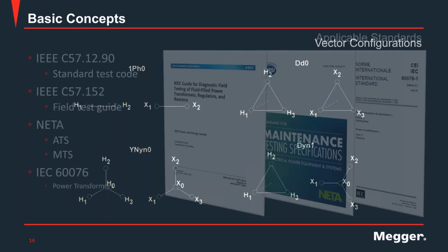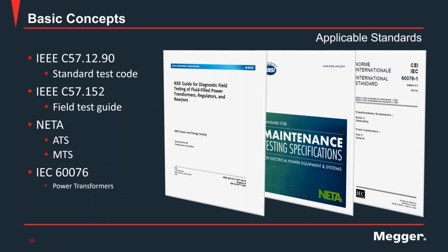I also mentioned that we need to compare these values to our nameplate and then determine if my measurements are within the limits. What are those limits? The IEEE dictates plus or minus 0.5% of error when compared to my calculated value from the nameplate, my transformer nameplate ratio.